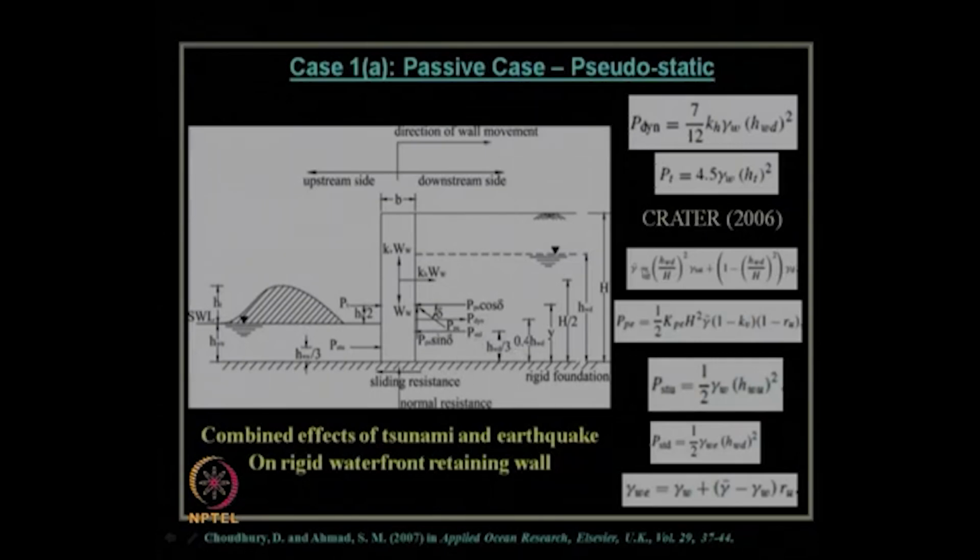Clear? How to estimate that hydrodynamic pressure? We used the equation given by Westergaard. As I said, Westergaard's equation for hydrodynamic pressure is very well known and commonly used worldwide, which gives 7/12 k_h times gamma_w times h_wd whole squared.